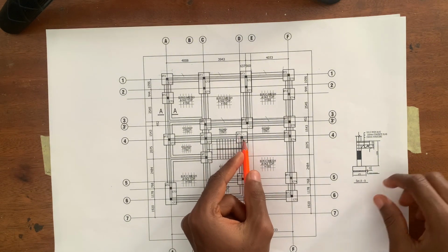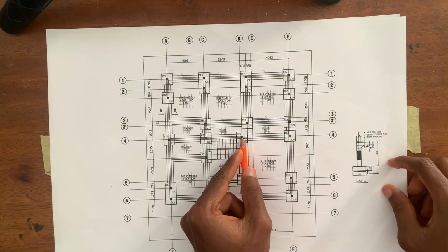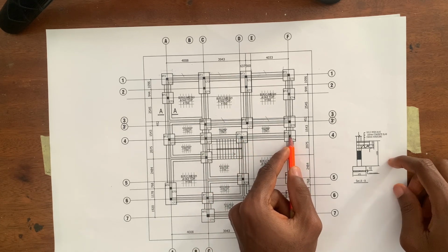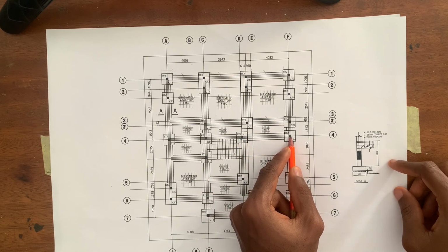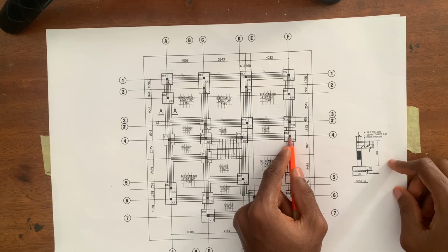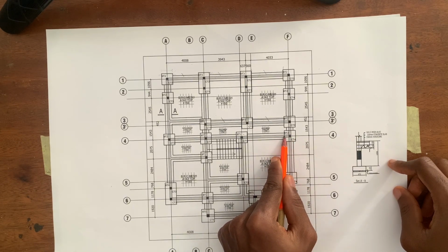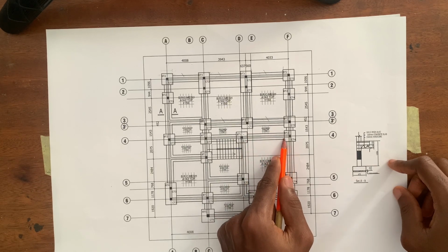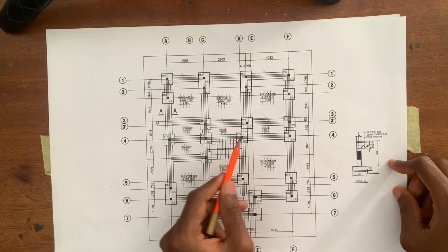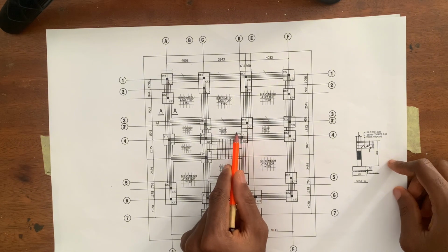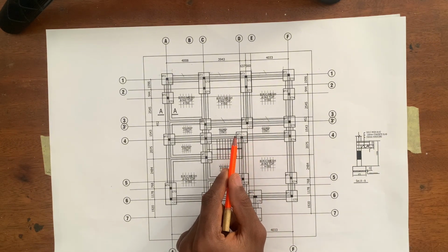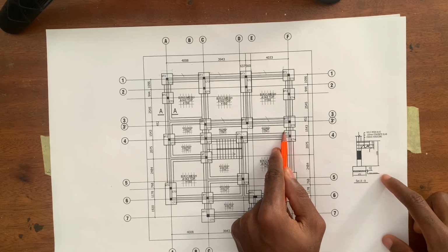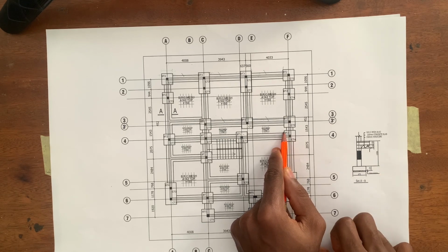So it means that the center to center dimension from the center of this column placement to that of this column placement is 5230. But that is not what we're looking for. We're looking for the dimension of the trench from the edges of the column pit. So what we can now do is this. What is the length of base type 1? It was given as 1200, and the same applies to our base type 2. Base type 2 was given as 1200 in the drawing.